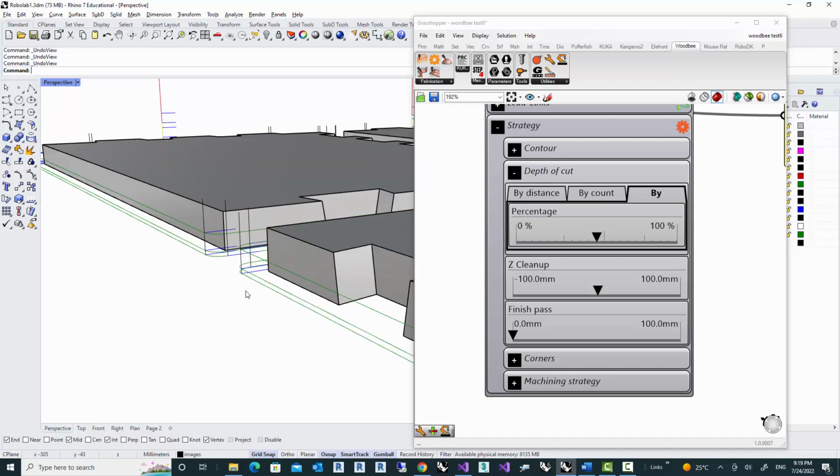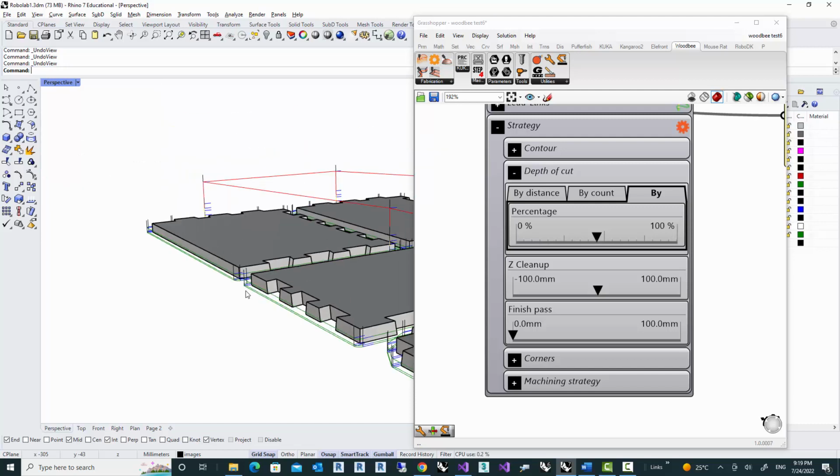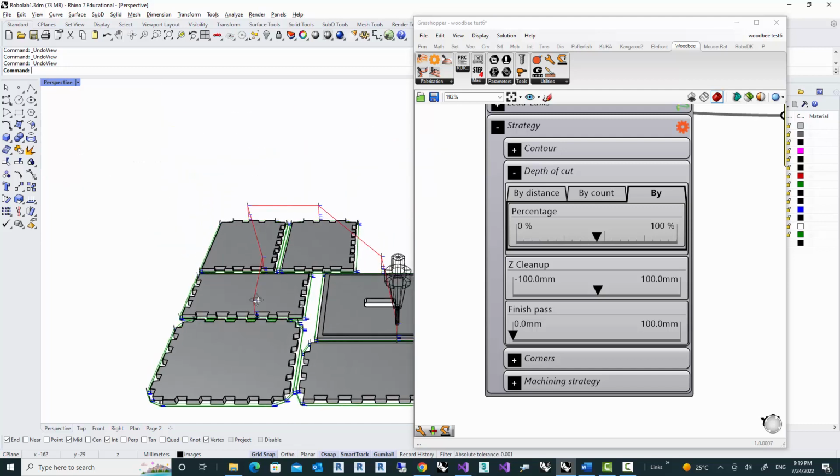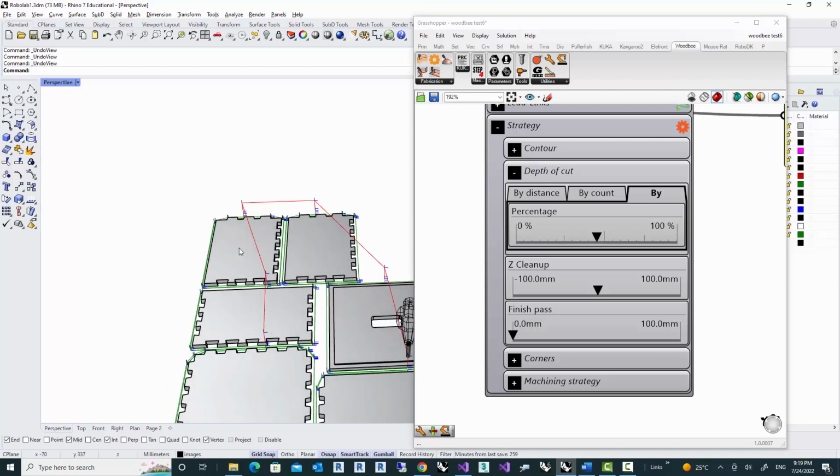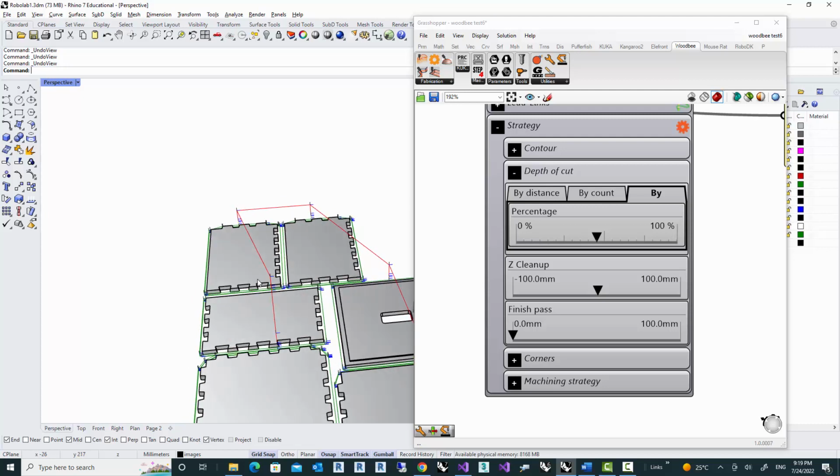You may find this useful because usually when you do fine milling, you probably want to go with a very minimum cut with the last pass in order to minimize the damage on the material. Or you probably have a big sheet of material and you don't want your part to be detached suddenly from the sheet, and then it could be that the sheet moves on the table or something.